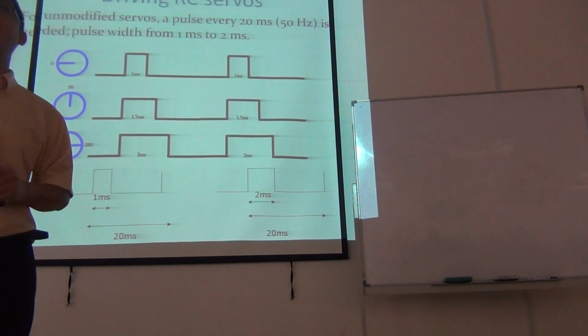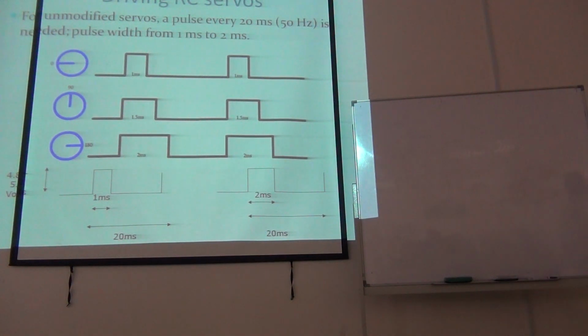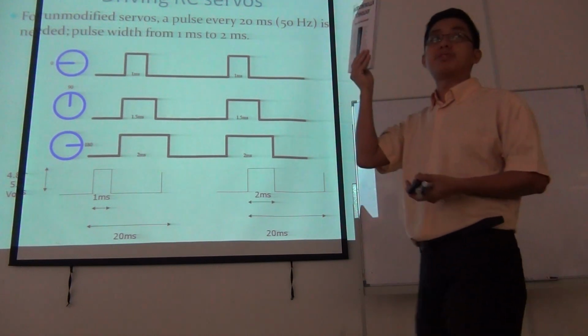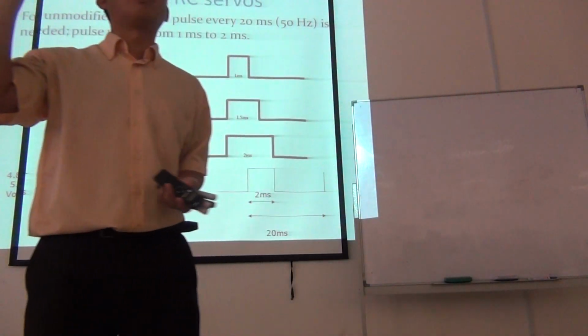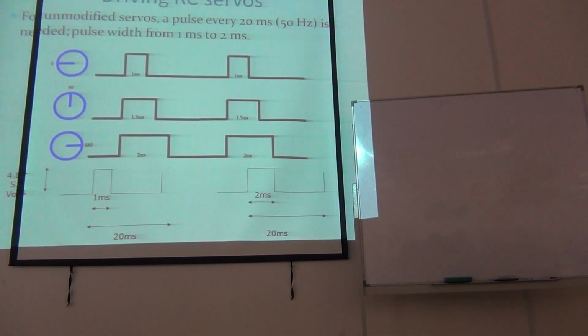I repeat, your CCP1 and CCP2 at port C are normally used for the DC control for the PWM. But they cannot support this type of PWM. So you have to create your own PWM to control it.